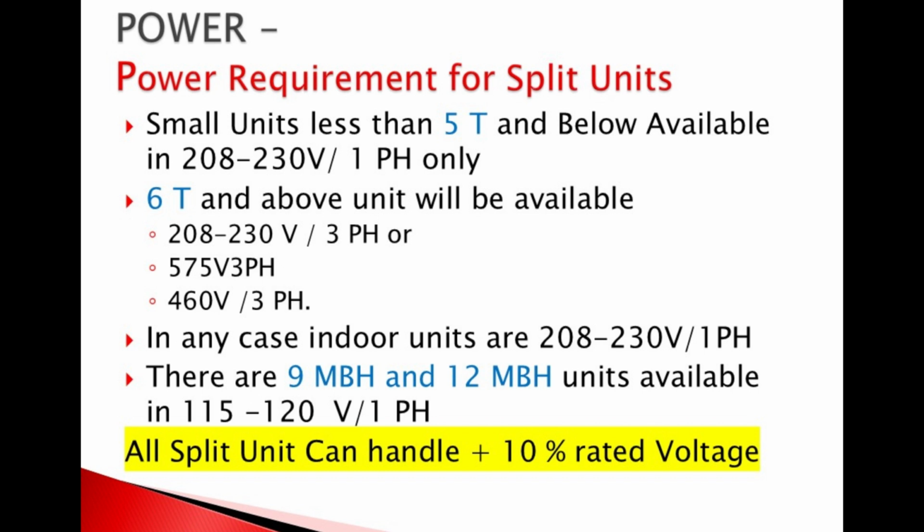These systems require separate power supplies for the indoor units, which typically run on 208 to 230 volts single-phase. This is especially true for VRF systems, although other systems can have the indoor unit powered by the outdoor unit.